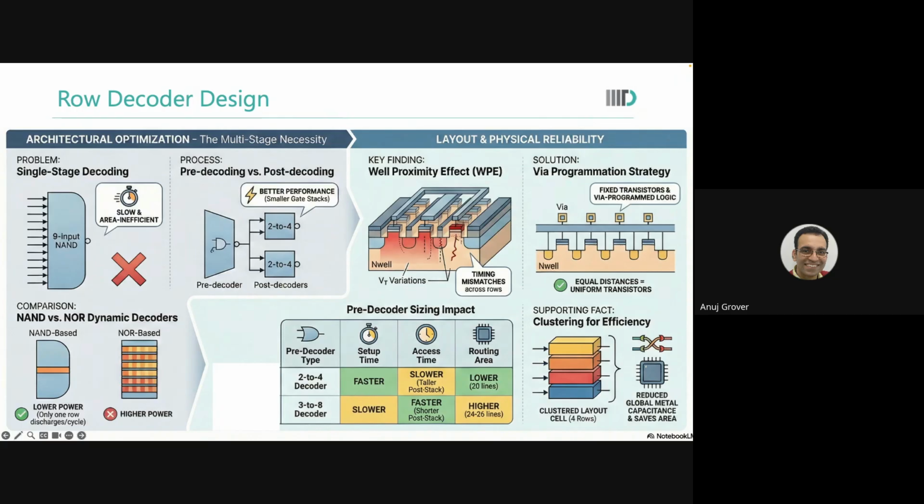For row 4 or row 16, let us say, one of these bits, instead of 0 going here, I may be sending 5 here. See, a decoder was giving me 8 outputs, is it not? So instead of connecting to the 0th output, I might be connecting to another output. But at this level, the same row decoding will continue. Look at it over here, the programming chart that I showed just before.